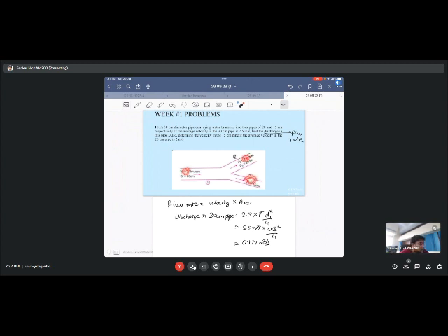the velocity itself does not get conserved. Velocity does not get conserved here. But what gets conserved is in fact the flow rate or the mass. So the mass of fluid here will be distributed in such a way that it is conserved when you add the sum of the masses distributed in pipes 2 and 3. So since this is a fluid or since this is water, we can assume that the density of water does not change.